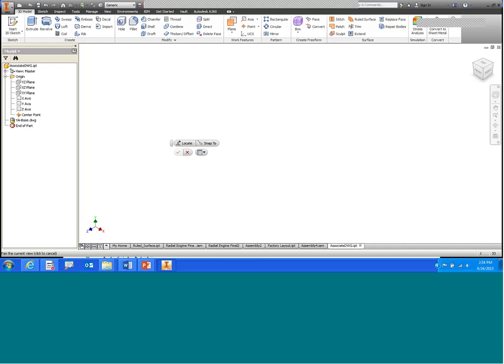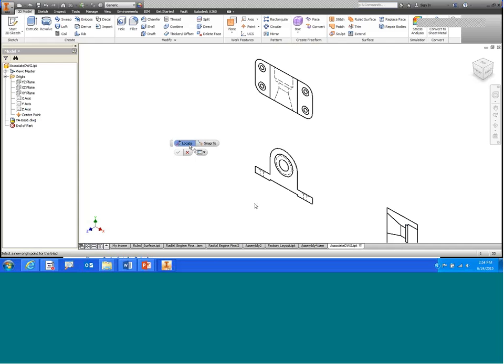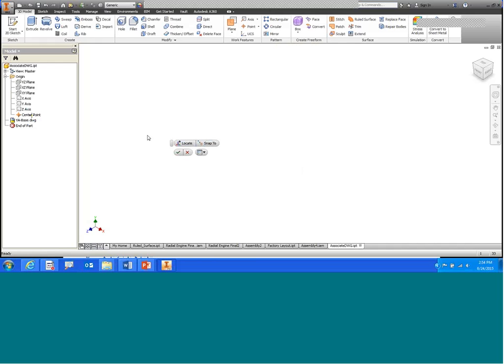So what I'm going to do here is just zoom in, and I'm going to say let's relocate this to the center of the model, and I'm going to say now snap to, so snap that center point to the center point of my actual new part file. And now when I select my home view, it'll actually be aligned properly with the center point of my XYZ plane. Okay, so everything looks great there.